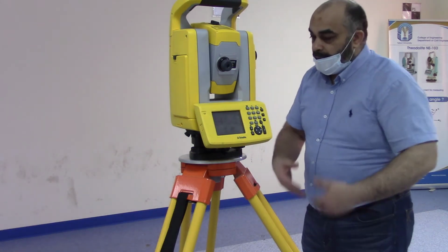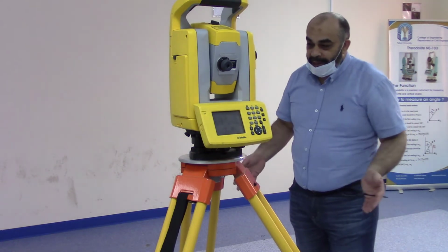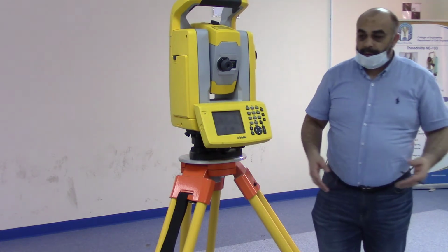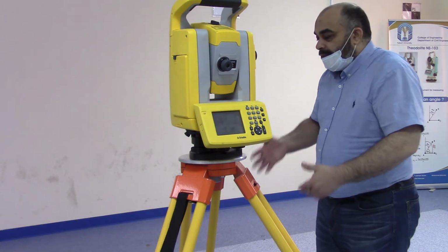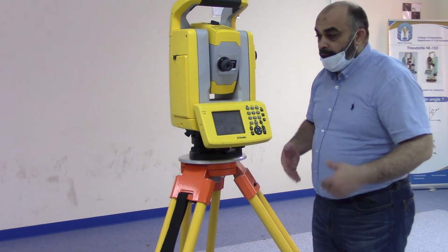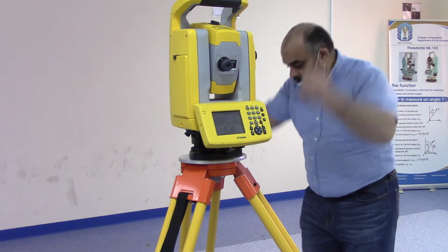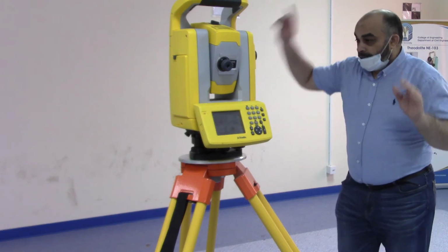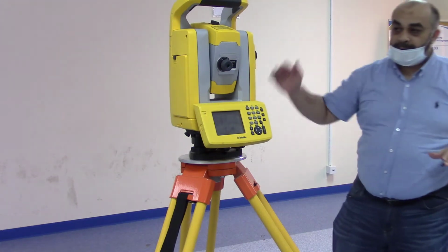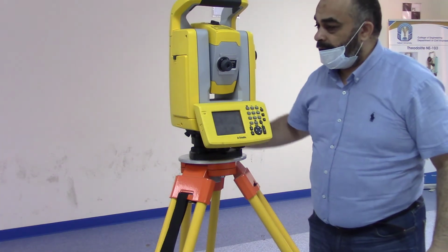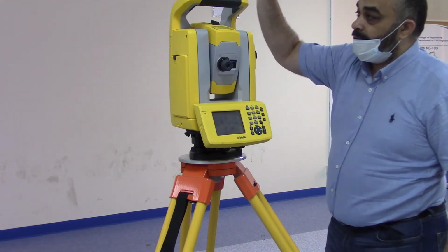Of course, the resection method is a method very used in practice, because in practice you will not all the time set up yourself on a known station. So in such situations you will in most cases use the resection method. Resection method means you place your instrument somewhere, and you have two points you will observe, with known coordinates: Easting, Northing, Elevation 1, and Easting, Northing, Elevation 2. Here we will enter the Easting, Northing, Elevation for P2 and after this for P6.